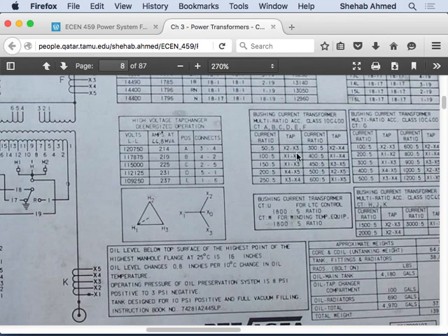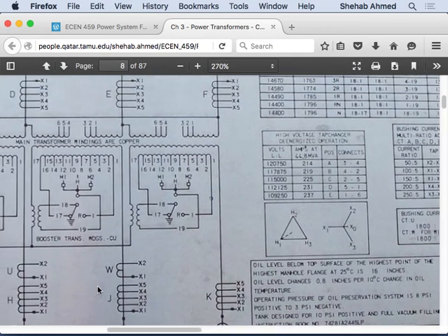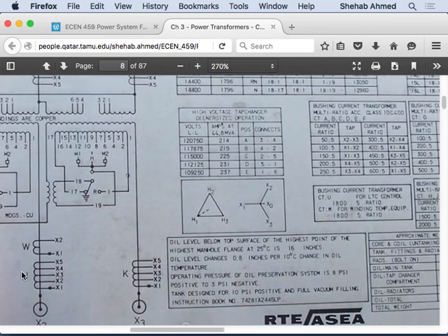Why do we have these current transformers installed in there? Because we will need to protect the device. When we talk about protection, we will see how we protect the transformer itself, and how we protect a larger power system, or a smaller part of the network. We'll talk more about that. But you will have some of these installed already. So that's what all these things on the incomings and outgoings are.